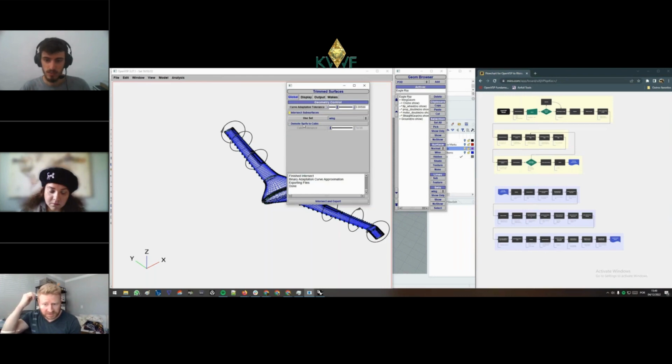Some CAD programs, being as they're kind of NURBS based as opposed to BREP solids, the direction of the curve kind of goes in a loop. And as long as it's closed, it's fine. CAD is fine with those two passing each other and it doesn't care, but they can't handle degenerate surfaces like a trailing edge being smashed down on itself. A STEP file is perfectly happy with that, but Rhino, Creo, SolidWorks, any of them hate that. And so if you ignore the trailing edge surfaces completely, you might not end up with any of these gaps or issues in the first place that could save you a couple of steps.